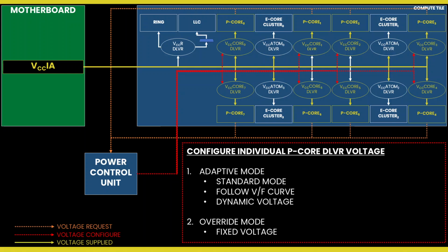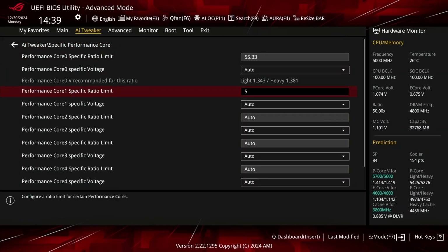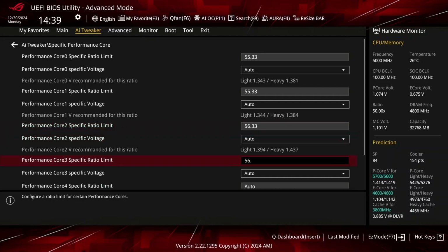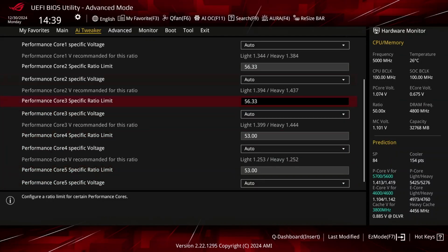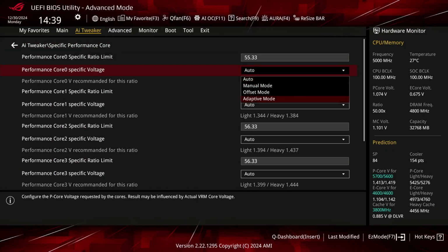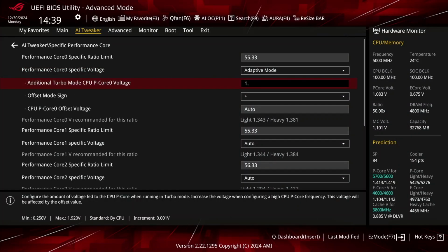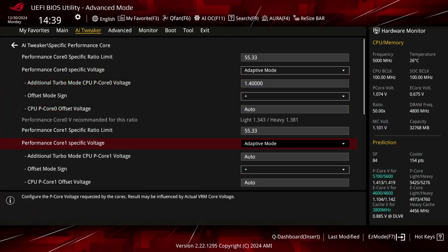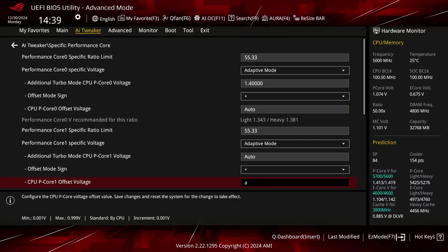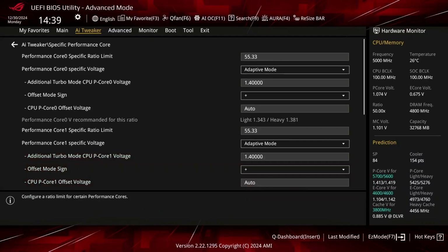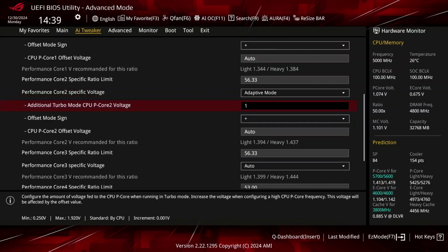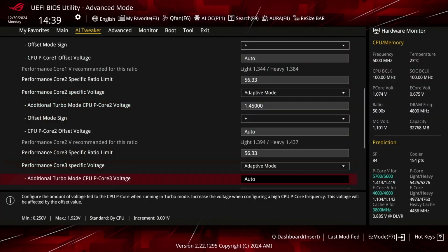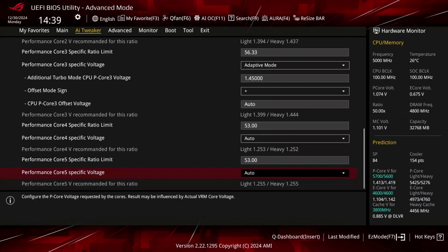The per core voltage implementation for Arrow Lake is slightly different than prior platforms, as each P core and E core cluster now has its own OC ratio. Functionally, that means every per core voltage is mapped to a respective per core ratio limit and thus also serves as the base voltage for VF.7. The standard rules for adaptive mode voltage, which we discussed in OC strategy number 2, still apply. As a consequence, it means that each P core and E core cluster's VF curve is truly independent, as voltage interpolation is done for each core individually.